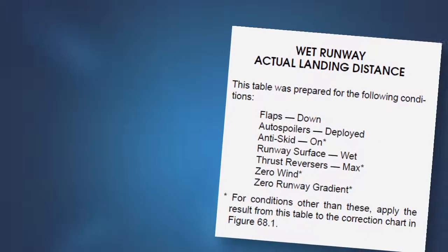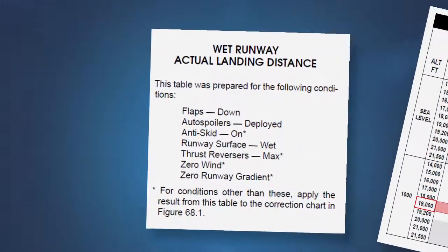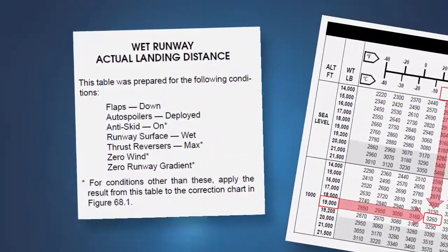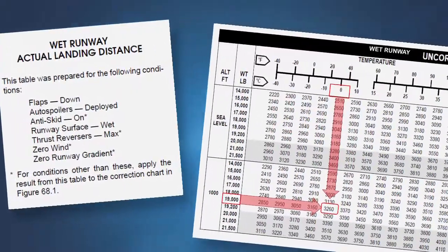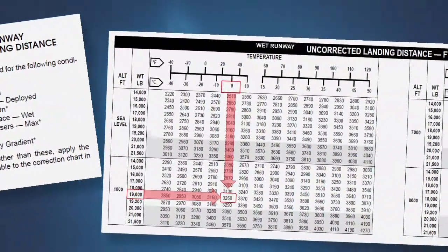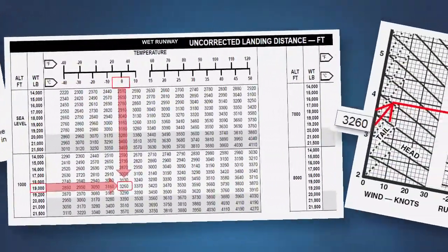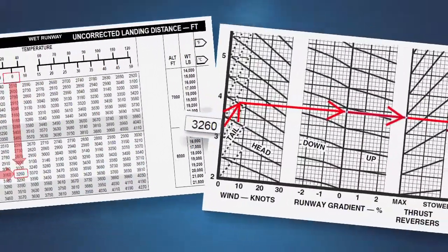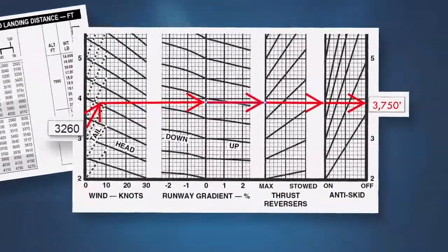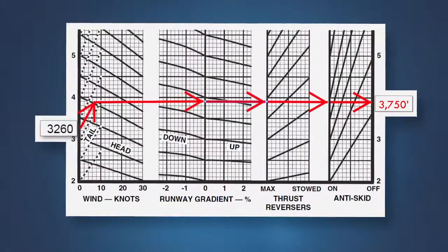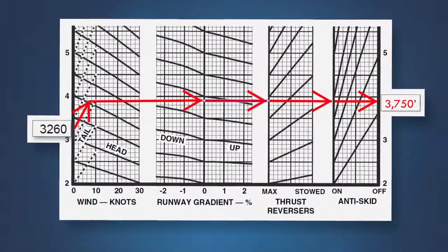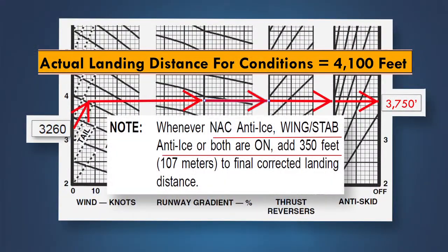The assessment may be based on manufacturer-furnished advisory landing distance data for use on wet and contaminated runways. This data is an analytical computation that adjusts landing distances determined during certification for the detrimental effects on braking performance resulting from a particular type of contamination. While the data is not based on actual flight testing, it does allow flight crews to assess actual landing performance based on the anticipated landing conditions.